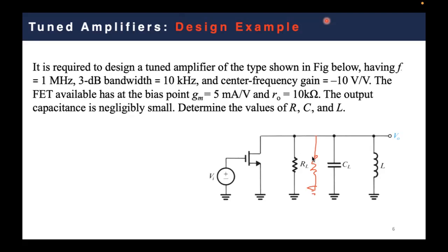We have the impact of r0. If you remember, r0 is the output resistance of the MOSFET, and this is usually considered whenever you have a realistic MOSFET model. Mostly in ideal MOSFETs, we assume r0 equals infinity, but in real measurements, we usually have this small slope that appears in the saturation region that can be expressed in terms of r0. But let's go back now to the concept itself.